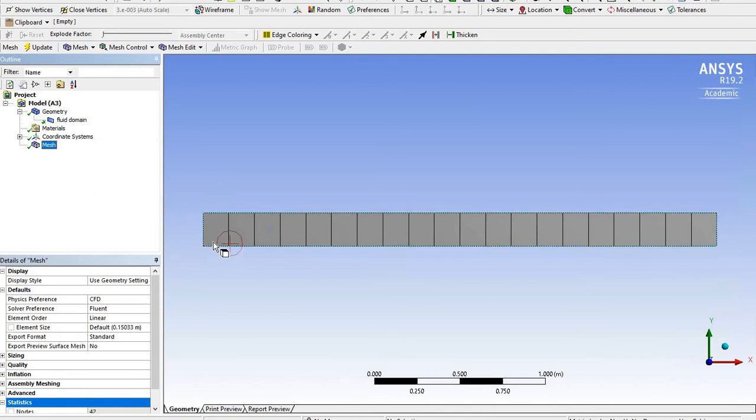So depending on the problem, you'll do the mesh. You want to do a very efficient mesh. You need to know where the critical region is in your problem, and in that critical region you want to have as many elements as possible. In this problem, we know near the wall, due to no slip condition, velocity will change by a lot. But in the middle there will not be that much of a change.